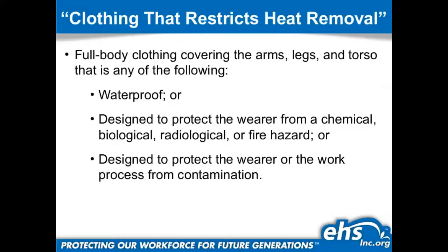Full body clothing: clothing that restricts heat removal, covering the arms, legs, and torso, that is any of the following: waterproof, or designed to protect the wearer from a chemical, biological, radiological, or fire hazard, or designed to protect the wearer or the work process from contamination. Not only waterproof gear or PPE like hazmat suits, but something as simple as heavy-duty coveralls, which are most common in the work field. Heavy-duty coveralls are a huge insulator and can greatly overheat the wearer, and therefore should be worn in even cooler environments. We'll touch base on this as we progress through in the next hour or so.